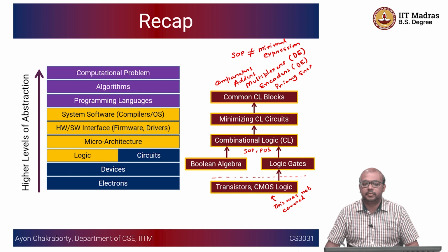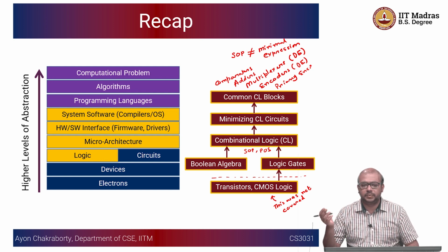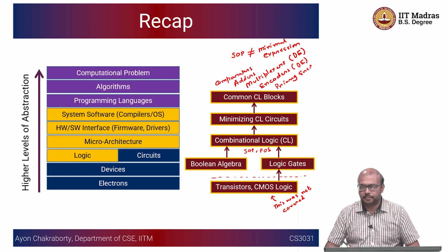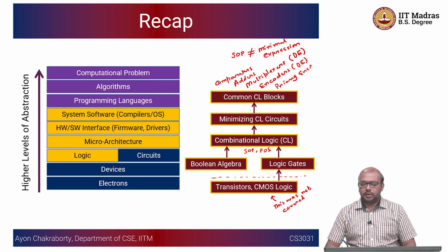So you do not have to create from scratch all the NOT and AND and OR logic. Sometimes you just get hold of a decoder and the decoder gives you all the min terms, and you mix and match those min terms according to your requirement, pass them to an OR gate, and get whatever is your expected output from the truth table and so on. Sometimes for this SOP kind of expression, decoders are very useful. So this is what we have learned.